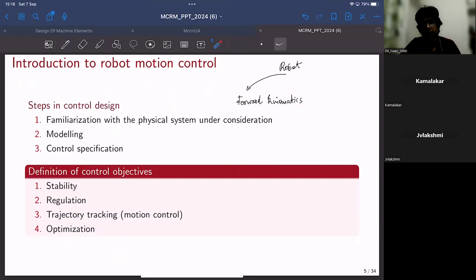Even if it is very difficult to visualize, you can actually plot, based on the DH parameters, how changing each of these joint parameters causes the robot or manipulator to move. So once you get the geometry of the robot, you can solve the inverse kinematics problem if you can exploit the geometry of the robot manipulator. Or you can also use some numerical schemes.